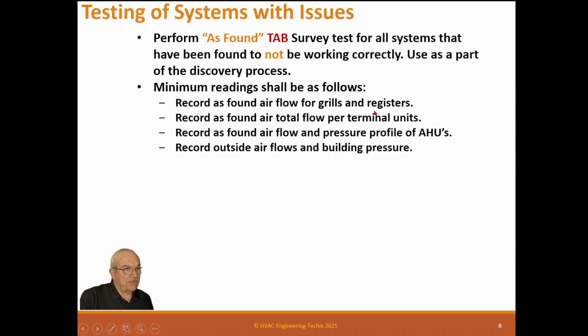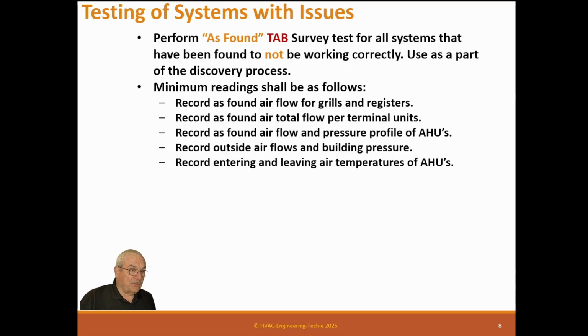So this process right here, you're going to need this for the terminal units because you got to calibrate the terminal units anyway. I guarantee you, unless the system has just been balanced, the boxes will be out of calibration. It's almost a guaranteed thing. It's something you have to check because not all of our jobs are actually done correctly. And if something's going to be done wrong, box calibration is number one suspect. So you need to check those anyway. And building pressure is another one.